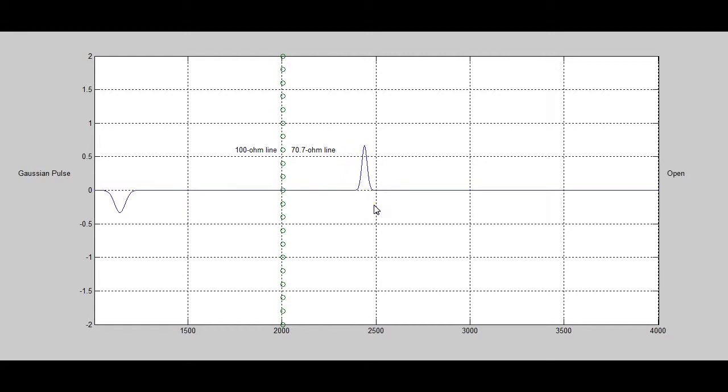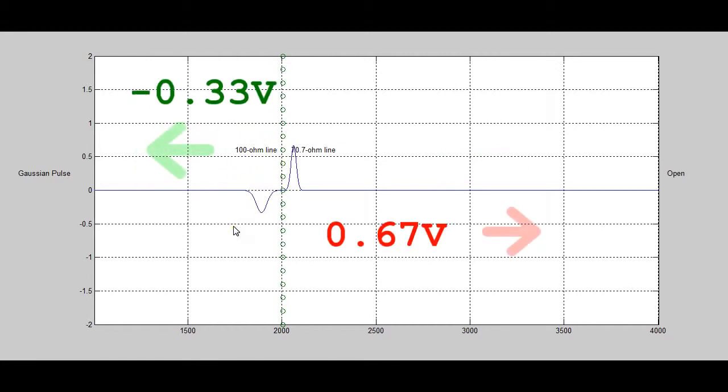When we hit the boundary, we saw some energy reflect. When you transition from a high-speed material to a low-speed material, we see a negative reflection coming off. The polarity flipped. Since we're traveling through a different material, we also saw the transmitted wave change shape. Here's that negative bounce again. Notice the magnitude of the transmitted wave goes down by the magnitude of the reflected wave.